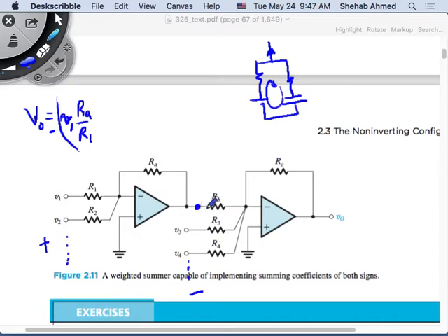But again, there's a following stage. And this one is negative, so it's positive. What do you mean negative? There is a voltage output here, an output voltage here, which is negative. No, it's not negative. If I have only the V1 input, it's negative V1 times RA over R1. Yeah, I see what you're saying. Since it's negative, they're all negatives here. Yes, I agree. Sorry, I didn't understand what you were saying. So the output here is a negative value. So it's an inverting amplifier, right?